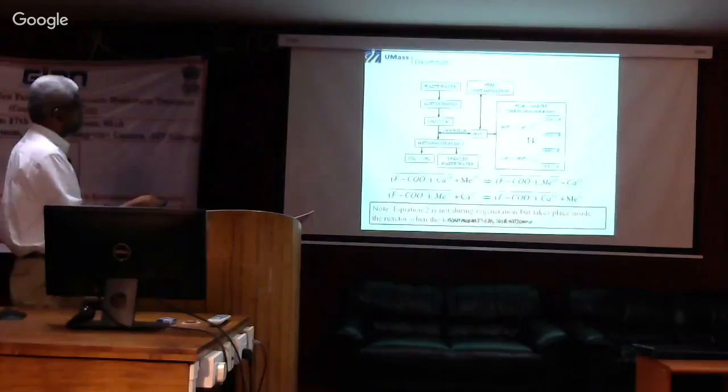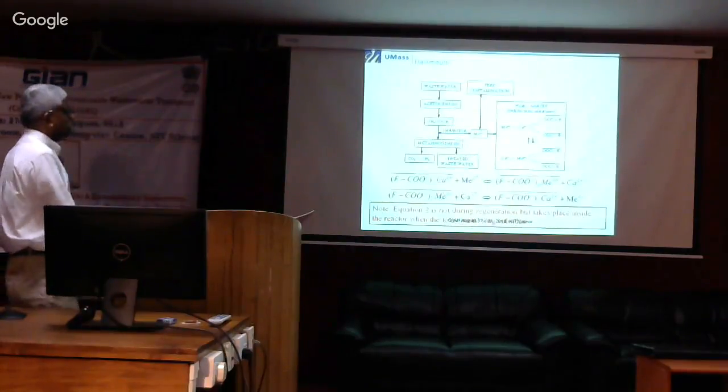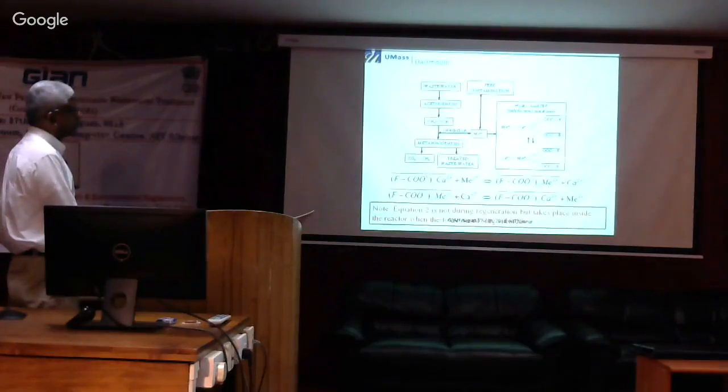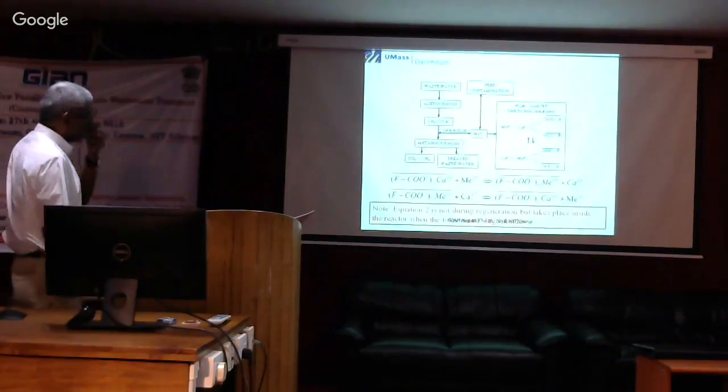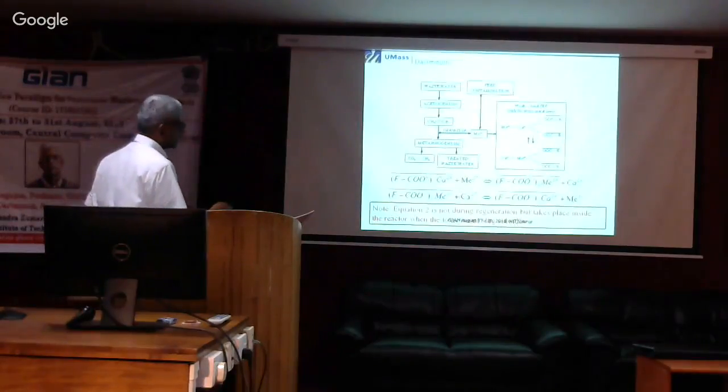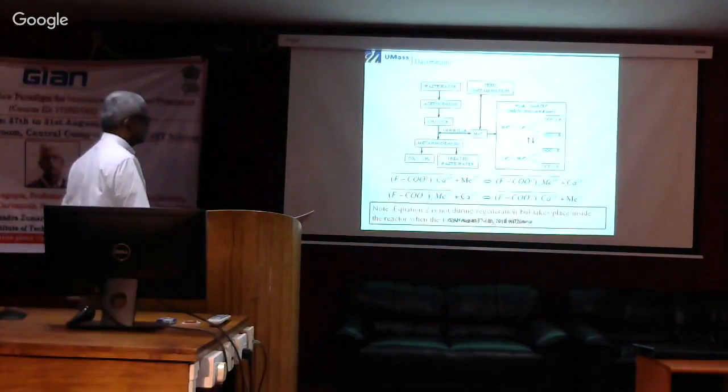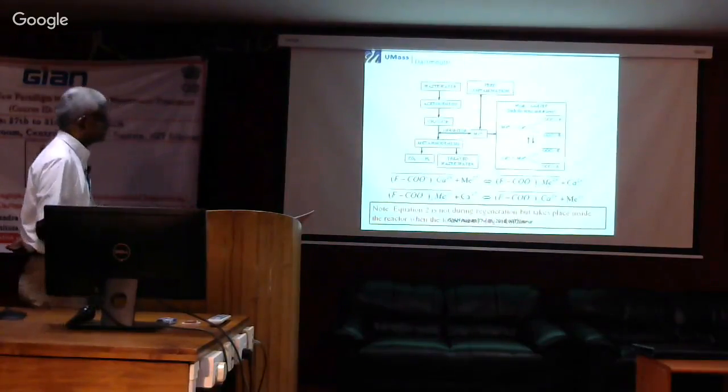So the wastewater goes into acetogenesis, forms acetic acid, goes into methanogenesis, forms methane and carbon dioxide. Now, if there is toxic metal in the feed, it will affect this process. If I put in this ion exchange fiber, then the fiber would be able to take up the toxic metal. And so you see it has, let's say it's originally in calcium form. It will then take up the metal, it will release calcium. Calcium is not a problem in the digester.